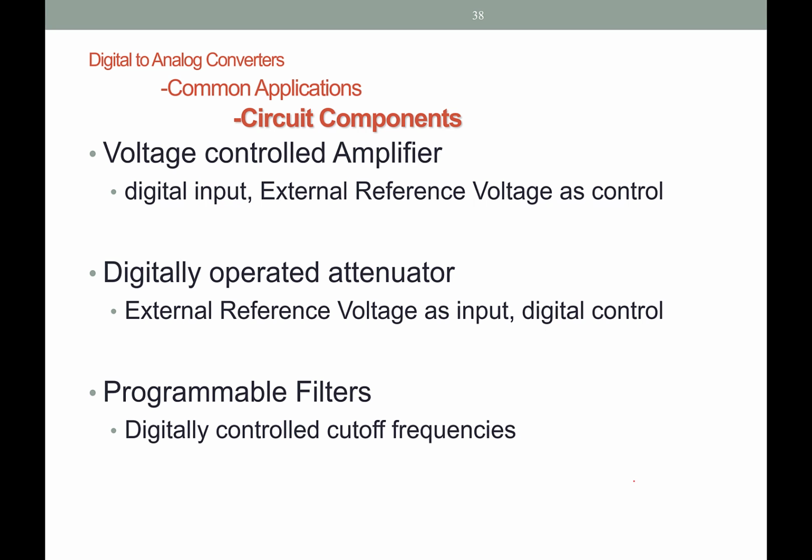Another application that was talked about over there was just circuit components, and there are uses of these DACs for something else. We can have a digital input and an external reference voltage as control for a voltage controlled amplifier. You might see that as a VCA referenced.